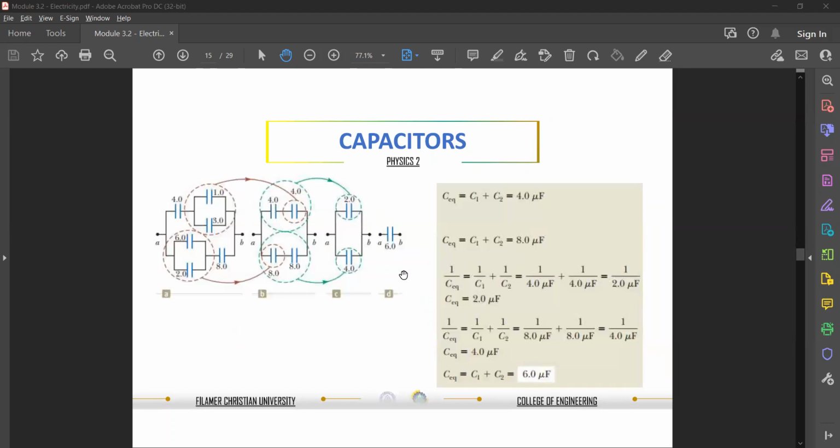And for example, we have here, so find the equivalent. Here we have 4 farad. Since these are in parallel, we just add them. This is a representation of how to simplify your circuit from A, B, C, and D. From A, let's combine first these, which are in parallel. So 1 and 3, that is 4. And then these, 6 and 2, so that is 8.